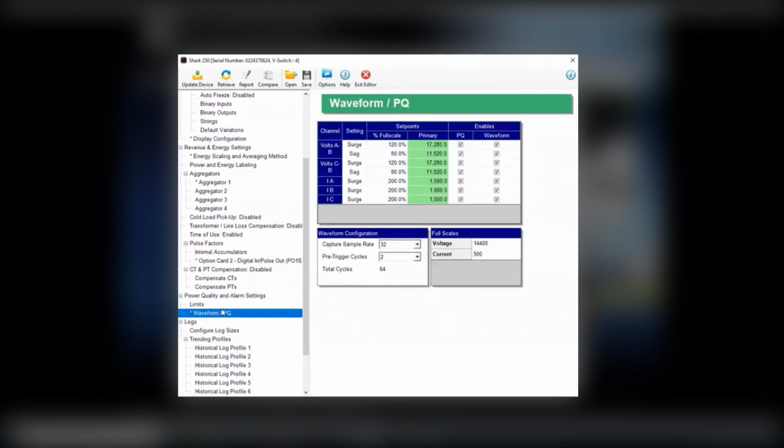Your waveform, which is another thing in this meter, it provides waveform capture, which gives you the ability to capture up to 512 samples on this meter, and that affects your total trigger size. So with 512 samples, you have 2 triggers, pre and post trigger, and this gives you the ability to control what you are trying to capture by setting the sample rate. So this is pretty nice. There are waveforms that are generated as a result of setting these parameters.